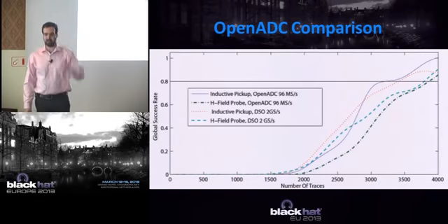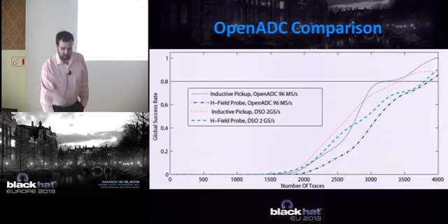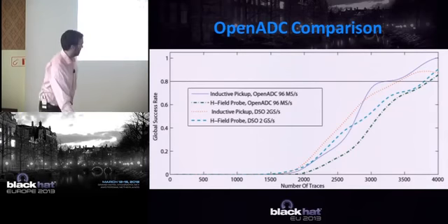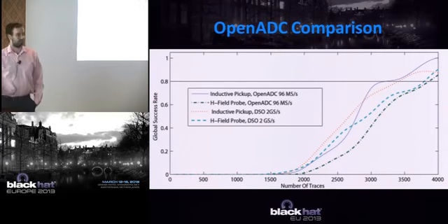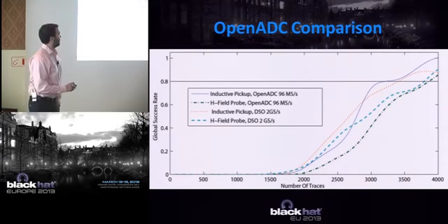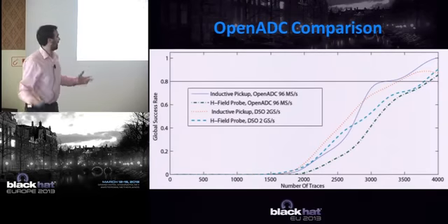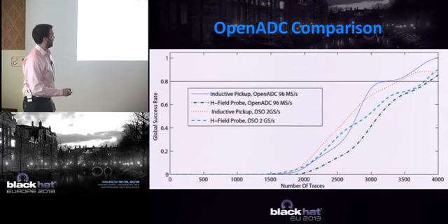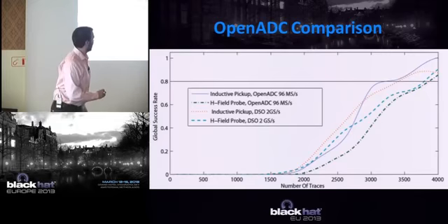So to make life easier, I've designed some open source hardware that can do this type of synchronous sampling. And this is just showing that it's basically achieving similar results. I'm using a 2 gigasample scope as reference, attacking this hardware platform, and it's achieving very similar results. So this global success rate is just saying, did I recover the key or not, averaged over a long time. So did I recover the key in 3,500 traces, averaged over a long time, and you can see they're crossing this 0.8 threshold, so 80% of the time I was right around the same point.